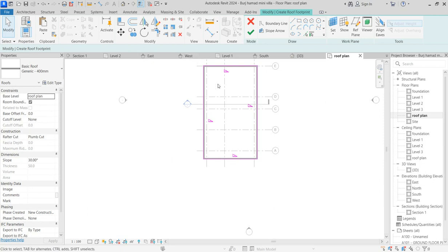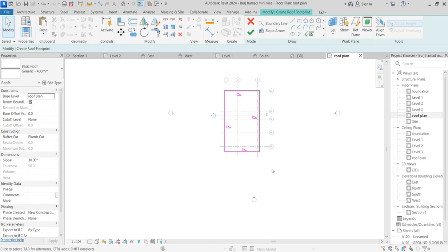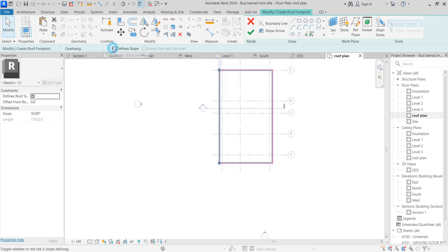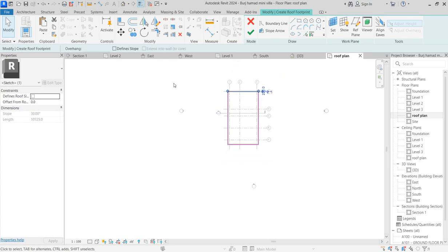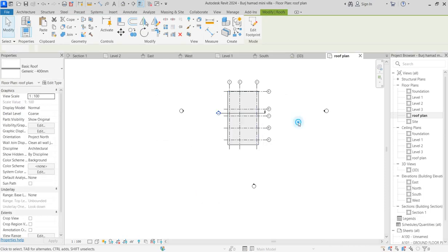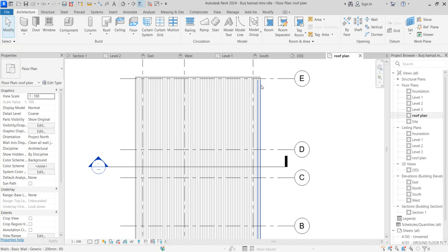So what we do here is that all the sloping arrows are going to go. Click on this define slope arrow. You click on this one again. There's only one that is needed, which is the side, the back side. I want it to flow and fall to the back, so not side. Side back is what I need here, and then I'm reducing this height to something like 3, which is okay for me. So attach it, let it flow around.